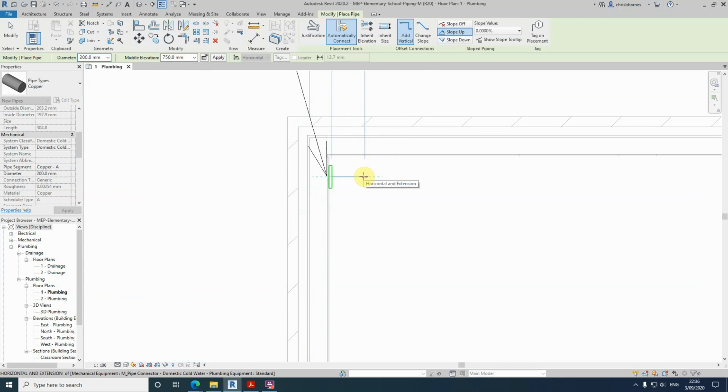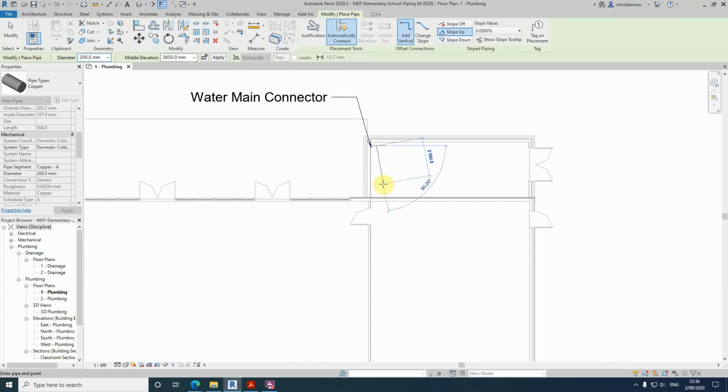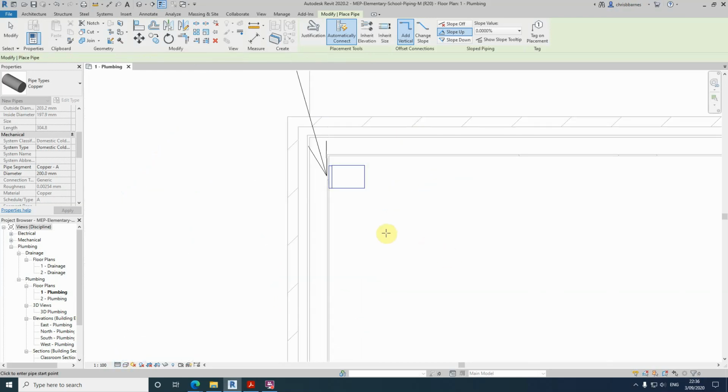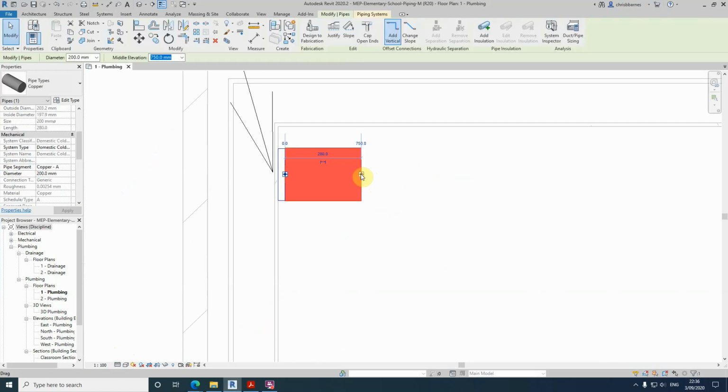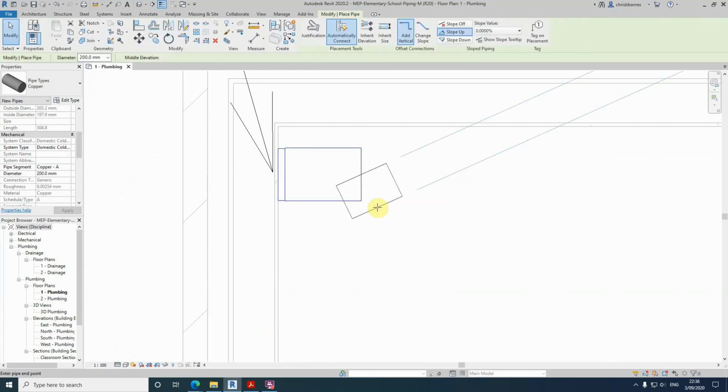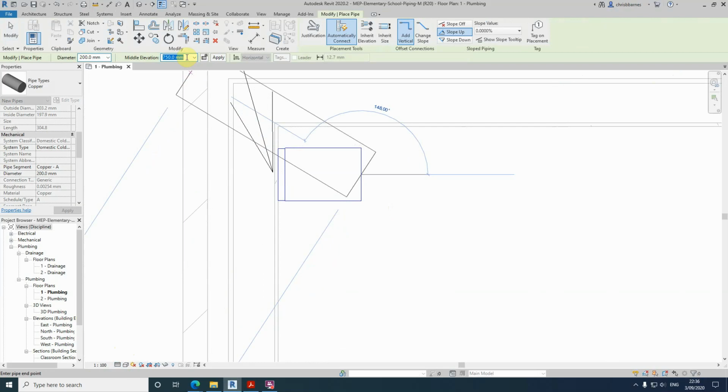Then we're going to draw a small way out, and then we're going to change our height to 3650. It's also probably a good idea to change our settings to fine at this stage. Doing that also meant that it loses connection here. So we need to go back to here, right click, draw pipe, and enter our height in again.